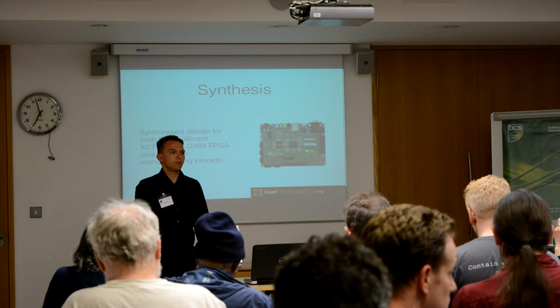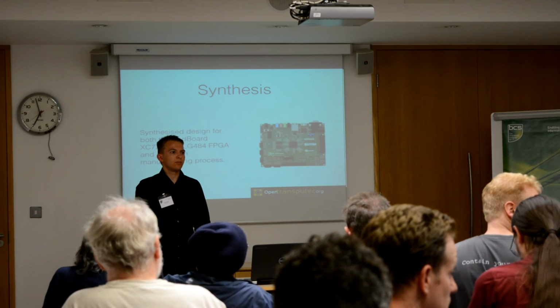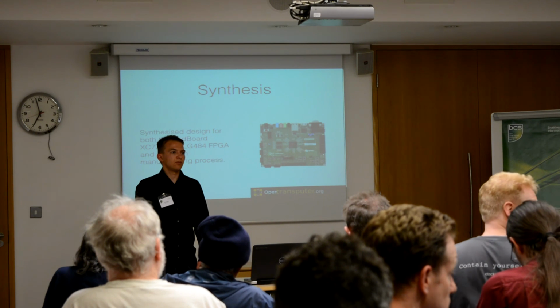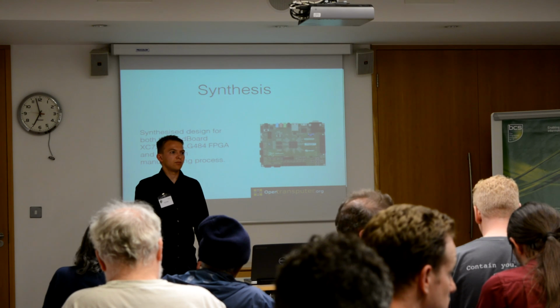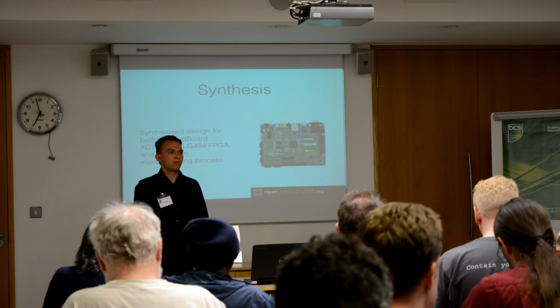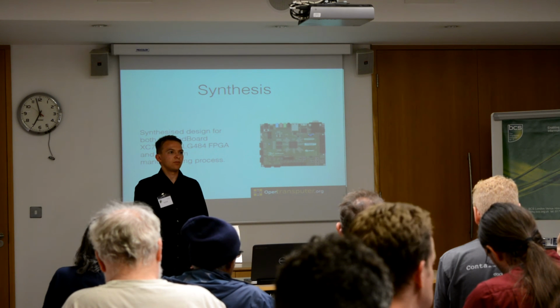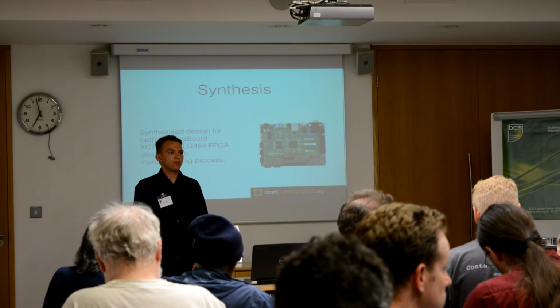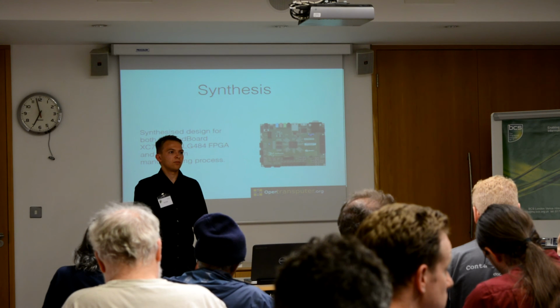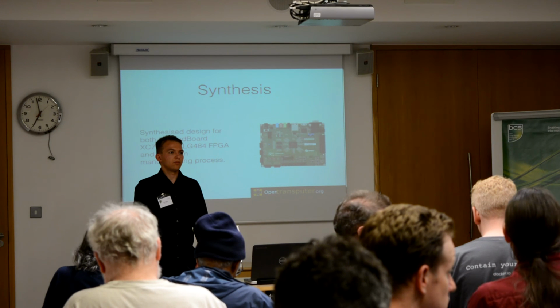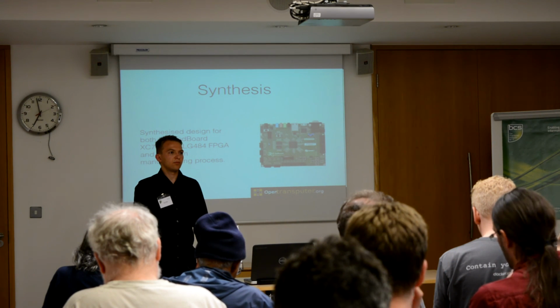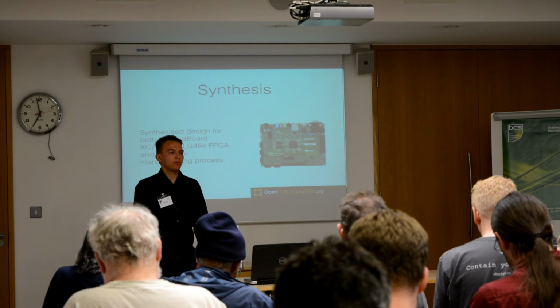So that means that the worst case performance of these instructions is dramatically reduced. They also have an improvement on the cycle count of a number of these instructions, which arises purely from the fact they've got more paths. So they can do more things at once within each of the scheduling instructions. So there are two contributory factors here. It was quite interesting. I never realised in the original Transputer design that we had been constrained to a significant extent in the way the microcoding of the scheduler was done. Because you can now move more data around at a time, it takes fewer microsteps for each of the scheduling instructions. So we've got a gain in efficiency there as well. So the scheduler is even faster than the original.